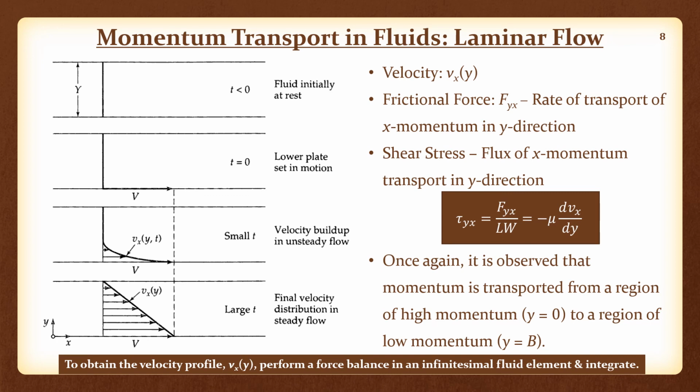And to obtain this linear velocity profile Vx as a function of y, one has to perform a force balance on an infinitesimal fluid element and then integrate. Of course, we will see how the momentum conservation equation is obtained and how it can be used to obtain the velocity profile in one of the forthcoming lectures. But performing a momentum balance or rate of momentum transport balance on an infinitesimal fluid element is something that you've been taught and are familiar with, I assume.